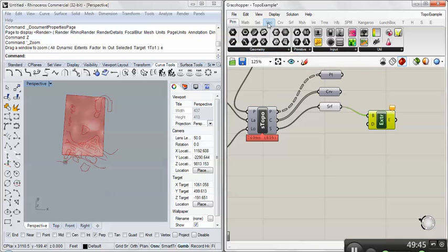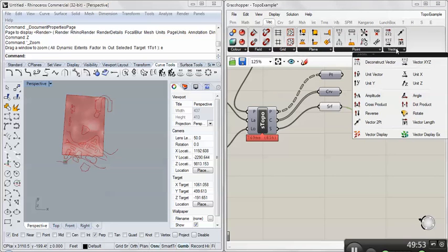So you want to construct a vector. So vector, luckily, is under vector. Here we go. So under the vector tab in the vector box, and we want this just to go in the z direction. The north and the south data was in the xy coordinate system. So we would just want to give ourselves volume so we can print it in the z. I'm going to grab unit z.